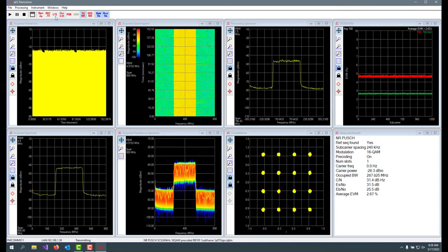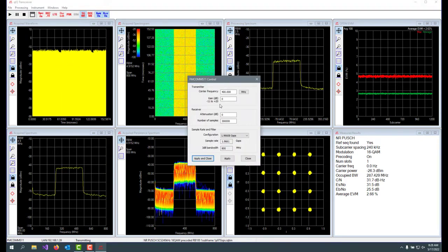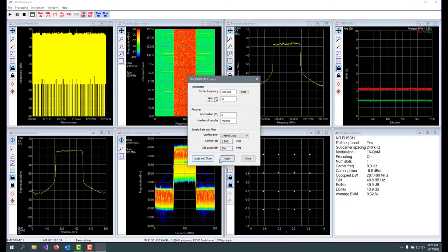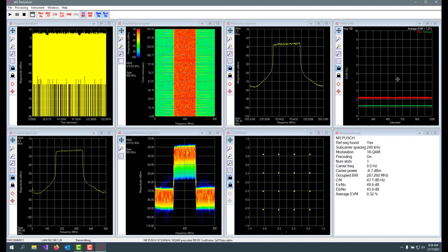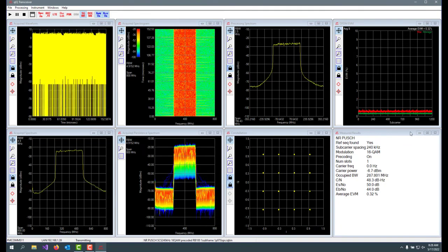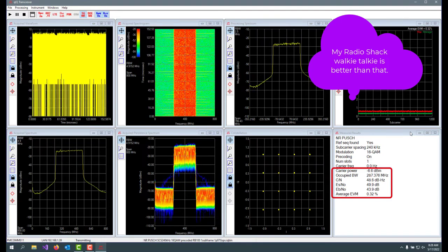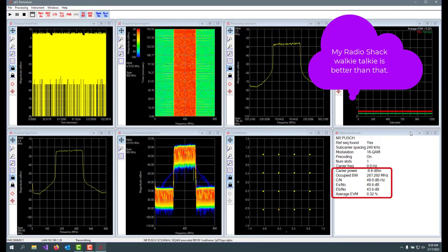Let's increase the transmit power to get a better signal-to-noise ratio. We will set the transmit gain to 20 dB. The EVM by subcarrier plot has averaging turned on, so it will drift to its new value. We can speed that up by resetting the averaging. So, we can now see that the EVM is around 0.3% and the ESNO is about 50 dB. For a bandwidth of about 290 MHz, that's very good.